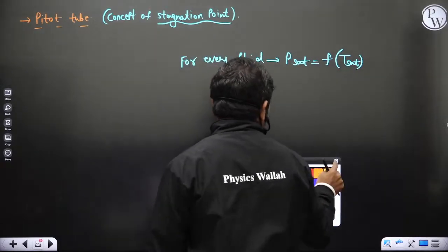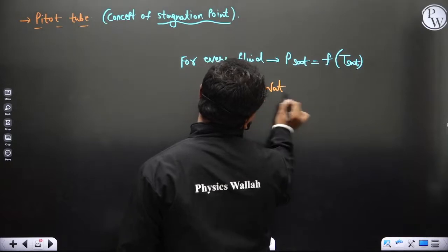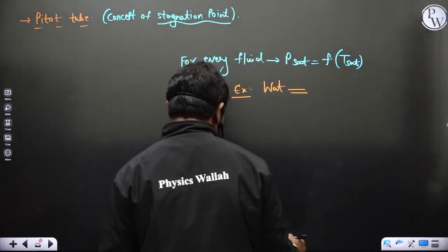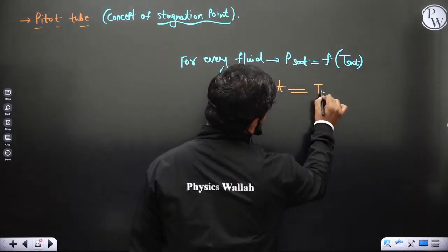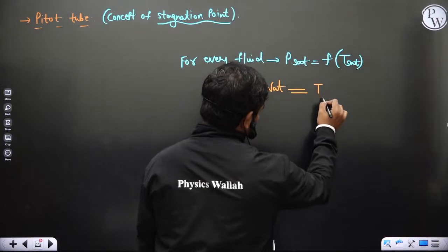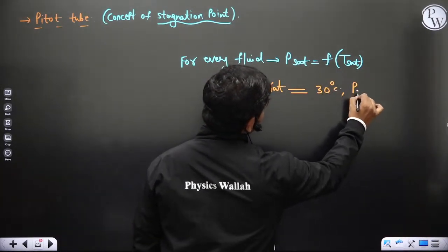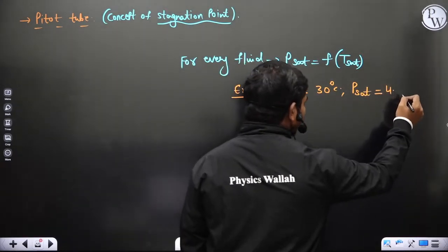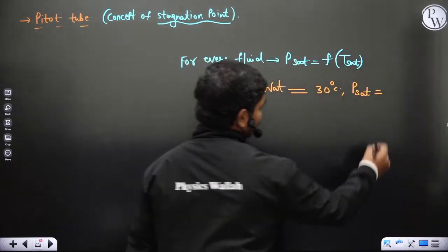So for water, for example, I don't remember the exact value, but at one atmosphere, at T atm or at 30 degrees Celsius, we have this P sat equal to something around 4.3 kilopascal, I guess. Anyway, I'm not pretty sure about this value, we have to take it from the steam tables.